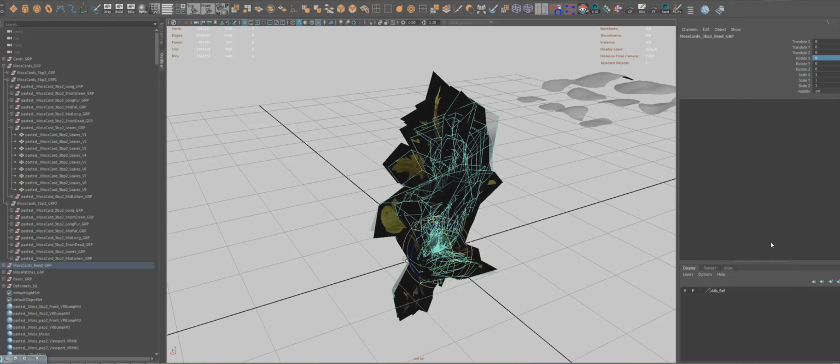Then we put the pivot in the origin point for each moss, rotated them and flipped them to have them in the same orientation all together, and then duplicated those ones and snapped them to the center of the board. Then we decided which one goes straight and which one goes flat, and then we assigned them some bend modifiers.